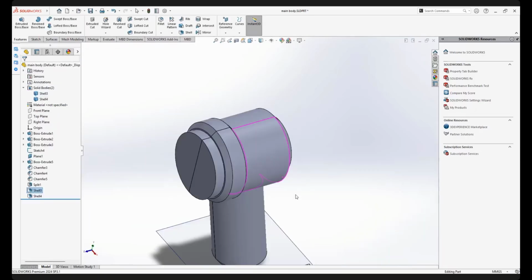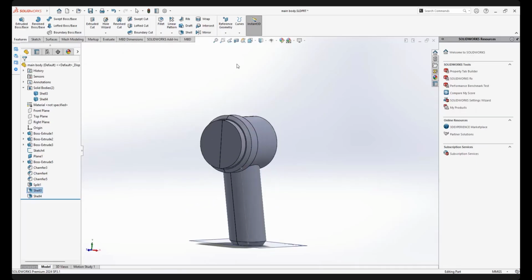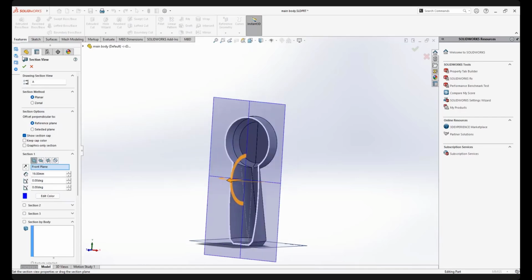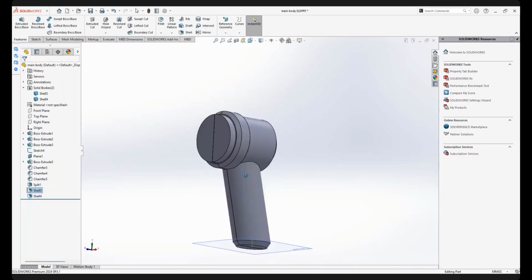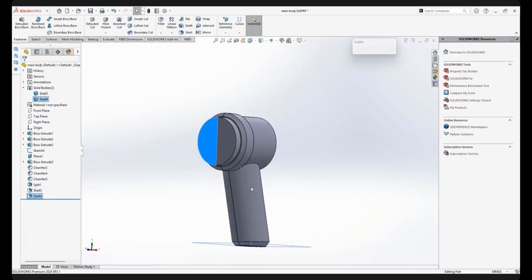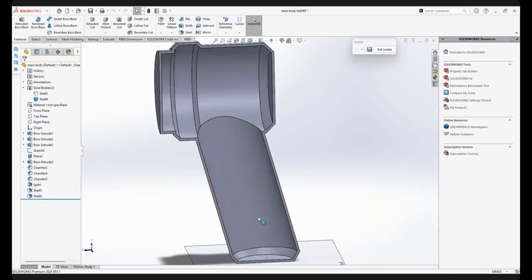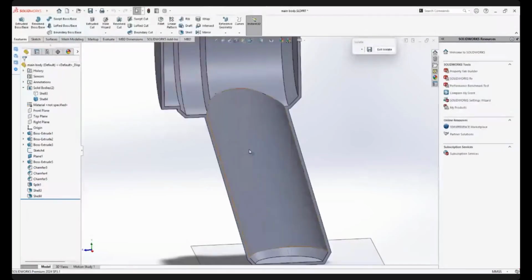So this is what you will mount. It is hollow because later you will do detailing. Here is where we will mount, so how do we mount the triple battery? Don't forget that when you dismantle your part, you will see a lot of complicated structure components. Do not forget about it. We redesign and make it simpler. So how do you make a battery at a 15 degree angle, and how do you make a rib to hold that battery? That battery can snap fit to that rib. That's pretty easy. I can show you later.